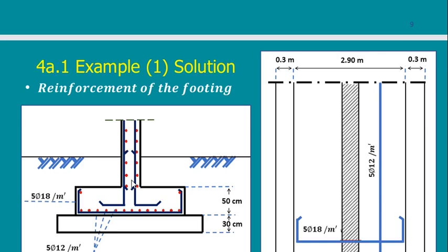Somebody would tell me, okay, why not shift the column inside to be in the middle of the footing? I will tell you. Imagine that this is the wall at the end of this class, that this wall is the end of your property, and you want to shift the column inside. It means that you will have the wall of the building, and then after it, with a meter or 2 meters, you will have columns inside. It means you will have columns inside your room. You cannot accept this from an architectural point of view. Your columns should be within the wall.